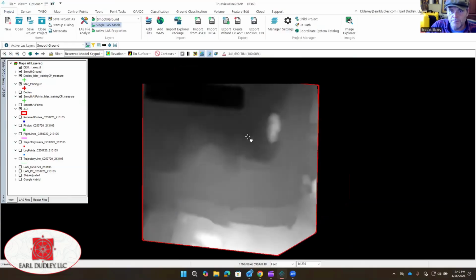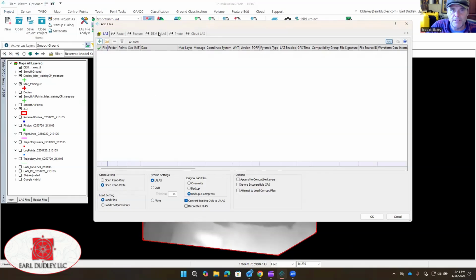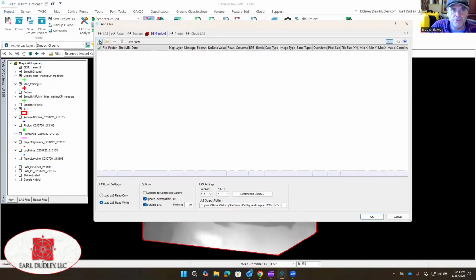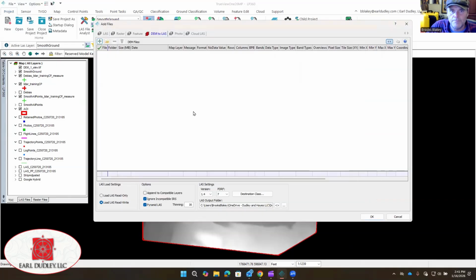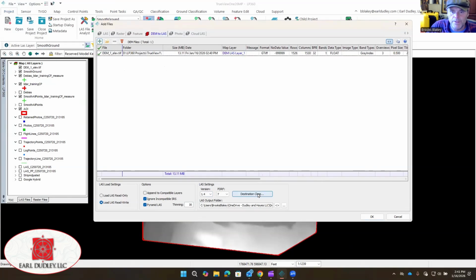Okay, there's our DEM. We want to go back to Project, add files, DEM to LAS. Let's go find that DEM we just created. There we go. Then down here, I'm going to select an output location.